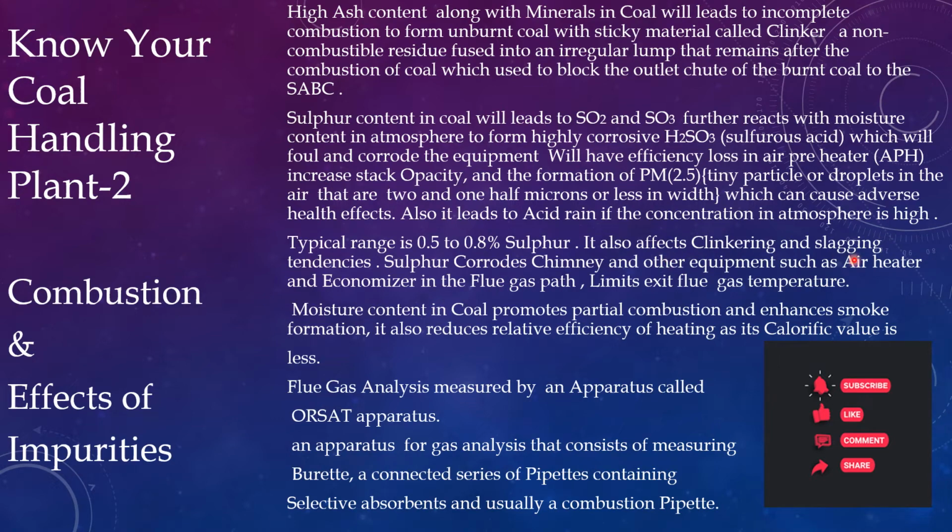To avoid this, we have to keep the flue gas temperature above 155 to 165 degrees centigrade while entering the chimney, or it should leave the chimney at more than 150 degrees centigrade, as the sulfur dew point is 143 degrees centigrade.